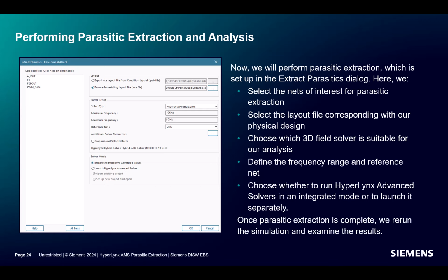Once parasitic extraction is complete, we return to simulation control and rerun the simulation with parasitics included. The results appear in the waveform analyzer, and we can overlay them with the previously obtained ideal non-parasitic waveforms for comparison.